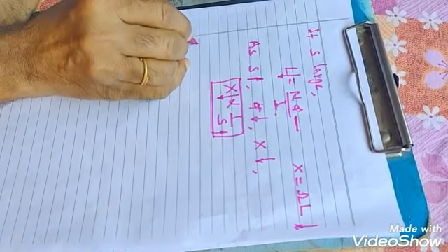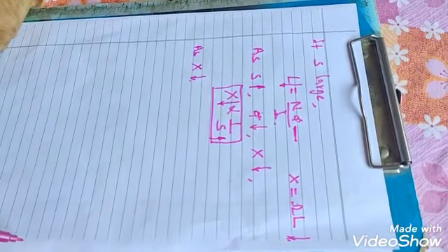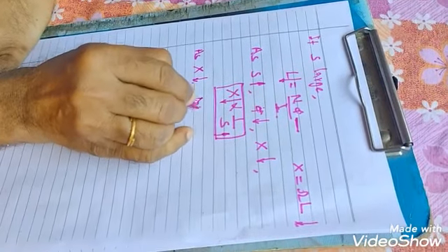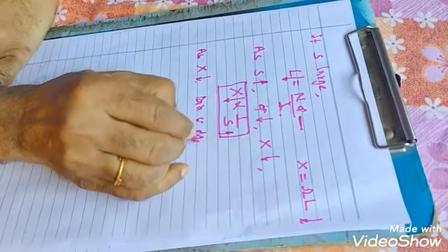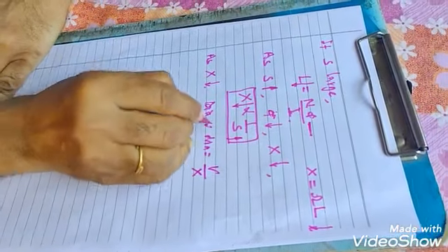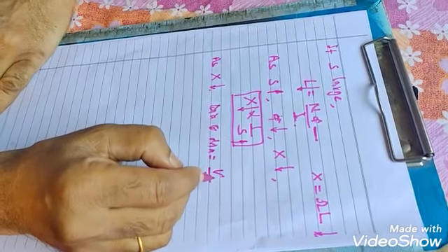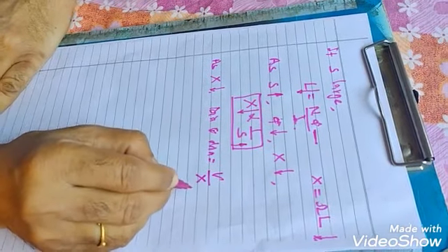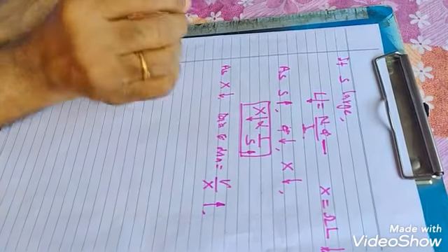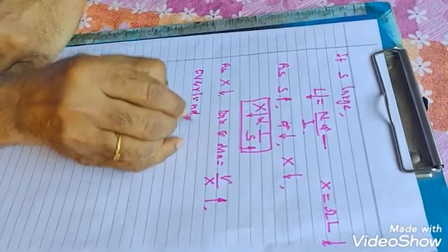And as leakage reactance decreases, the diameter of the circle diagram increases. The diameter of the circle diagram is V upon X. V is constant, so as X decreases, the diameter of the circle diagram increases, so that the overload capacity of the motor increases.